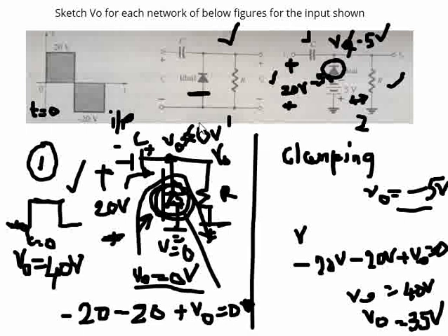One rule of thumb: start with the case where the diode gets forward biased, and then go to the condition where the diode gets reverse biased. You need to know when the diode gets forward biased and when it gets reverse biased, and KVL is very much required. With these scenarios, we must be able to analyze this circuit. It is a typical analysis, but with very simple rules of thumb we can do it.